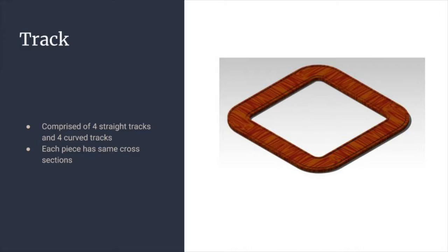This was created by simply making a profile in the part design workbench and then extruding said profile. The addition of the male and female connections came after. The curved track piece was a little more difficult, but not too far-fetched. It started off the same as the straight track piece, but instead of extruding that profile, a curved line was drawn. The rib command was then utilized to make a curved extrusion. The hardest thing about this part was making sure the curve wasn't too steep.